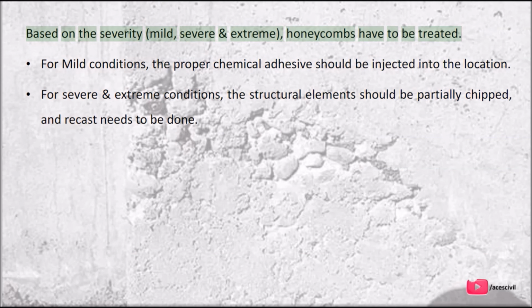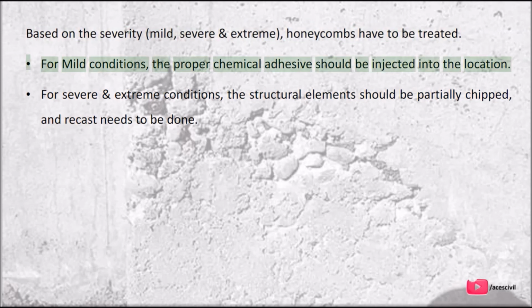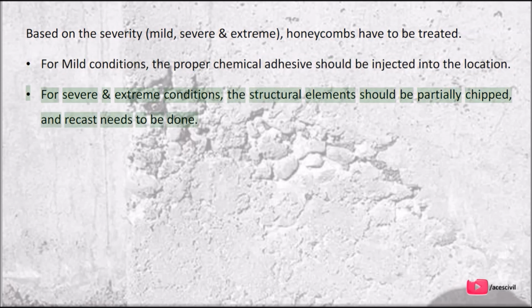Based on the severity, mild, severe and extreme, honeycombs have to be treated. For mild conditions, a proper chemical adhesive should be injected into the location. For severe and extreme conditions, the structural elements should be partially chipped, and recasting needs to be done.